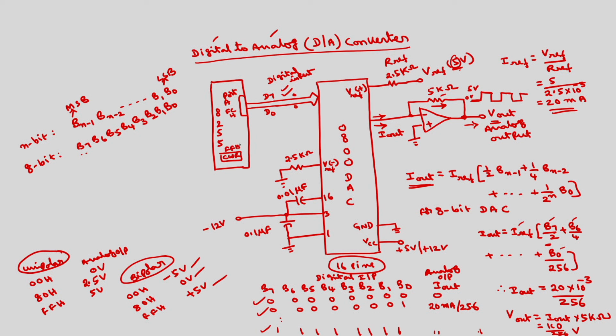So to generate square wave, what you have to do is first you have to program port A as output port. Move AL comma 80H, 80H will program all the ports as output ports in mode 0, which we have discussed in earlier lectures also. Then you have to out onto the controller register whose address is FFH.